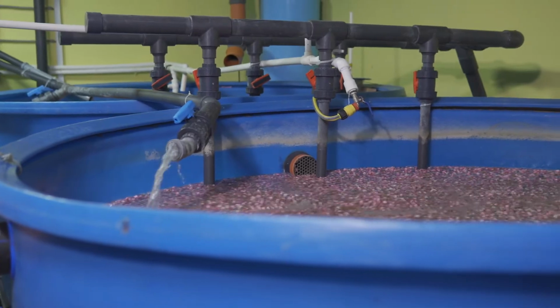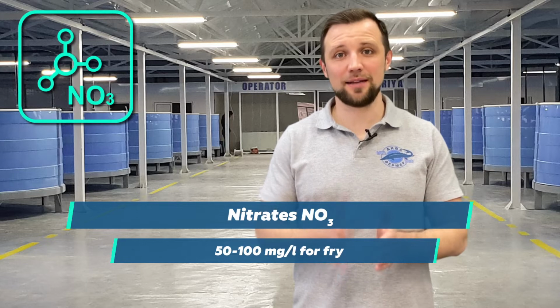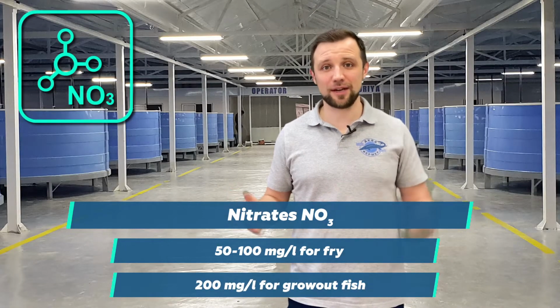Nitrates. Well, they are much less toxic than ammonia, nitrogen, and nitrites. They are the products of water treatment by bacteria in the biofilter. Nitrates accumulate in the system and can be removed only with flushing, unless, of course, denitrification is provided for. The normal value for fry is 50–100 mg per liter. For grow-out fish, it's 200 mg per liter. In general, when these parameters are exceeded, fish also become stressed and grow slower. So it's recommended to maintain normal levels of nitrates in accordance with the figures which I have just provided.